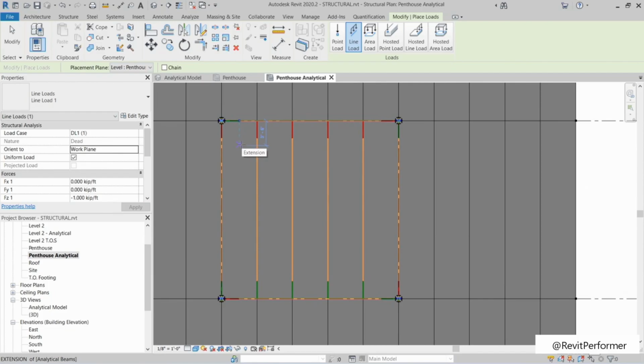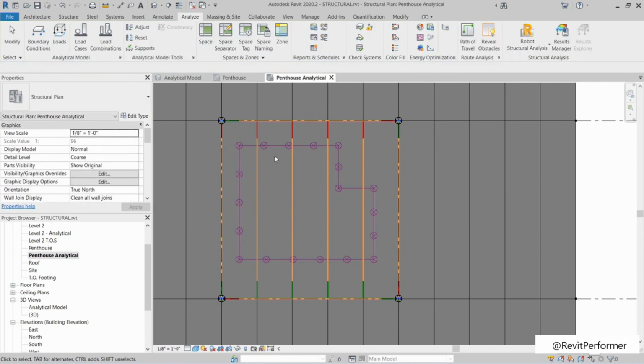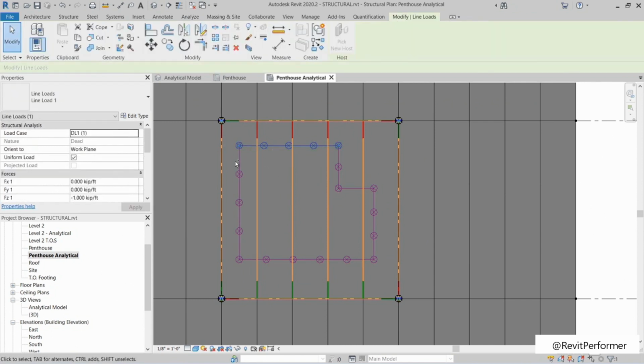Now we can basically draw any shape we want. Click the chain button, it makes it easier. Point here, over to here, onto here, over to here, up to here. Now if you hold down your control key and select all of these, our load case, we can change that. We can hit the drop down here, put that on AHU9. Go to a 3D view.